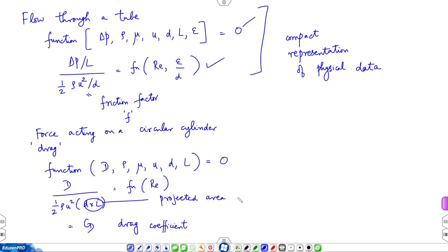So, it turns out that within the extent of uncertainty in the measurement data, you can use that relationship derived for a perfectly circular cross section, extended to non-circular cross sections by replacing d by hydraulic diameter.